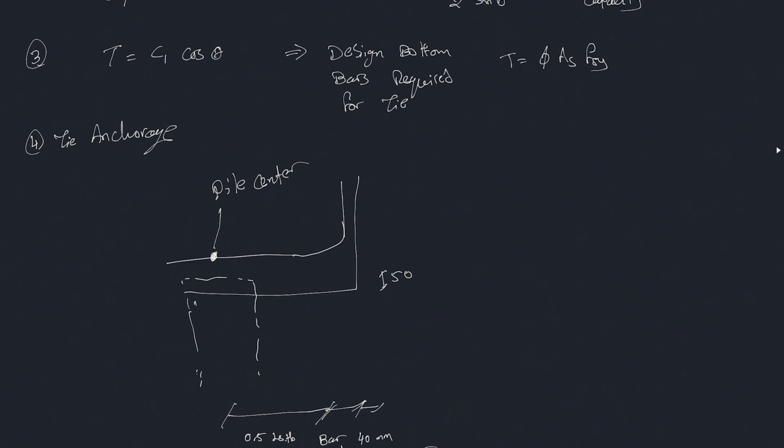And as always, remember to size the length of your 2 pile pile cap sufficiently to develop the bars in tension beyond the center of the pile. This distance is really critical, and it usually governs how long your pile caps need to be. Generally speaking, you will need at least 300 from the face of the pile. That is the absolute minimum. Sometimes you'll need bigger than that if you have very heavy bottom bars that need a longer development length. You can always cog your bars to get only half of the development length that you need from the face of the pile.